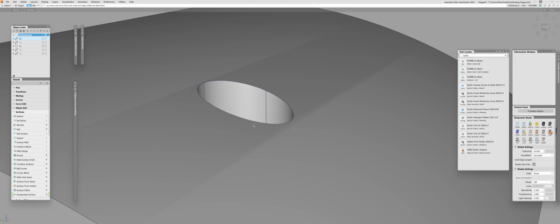Now, of course, most polygonal modeling software, if not all of it, doesn't really understand or work with NURBS geometry, except Blender. It has some B-spline options, but not a lot of NURBS geometry, or NURBS curves as they call it. But doesn't matter, I digress. So the proper way of doing it is to export this to a different type of file format, which tessellates and converts it to a mesh, basically baking it to a mesh, removing all the NURBS geometry data and leaving only the mesh.